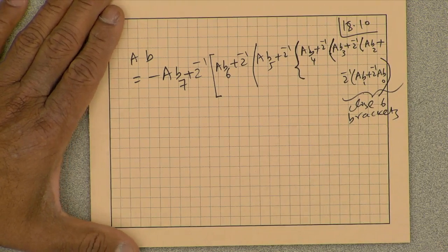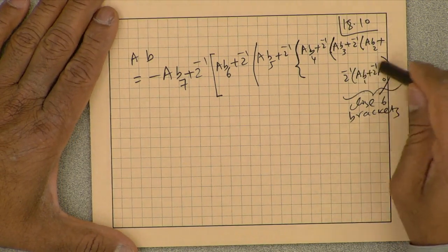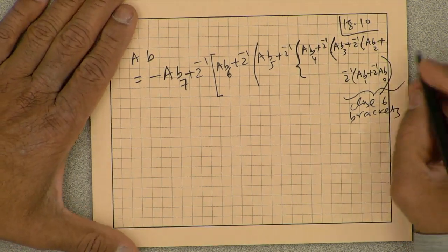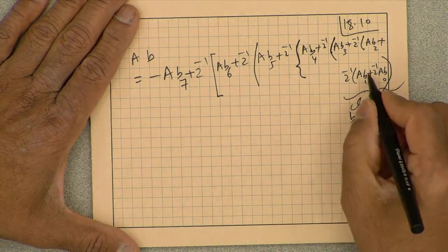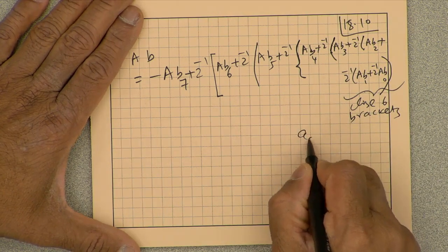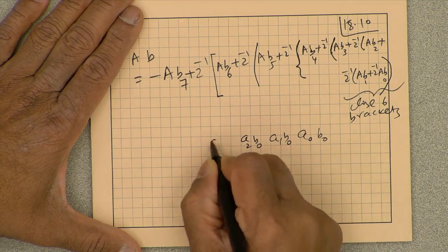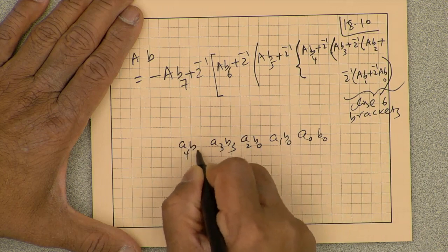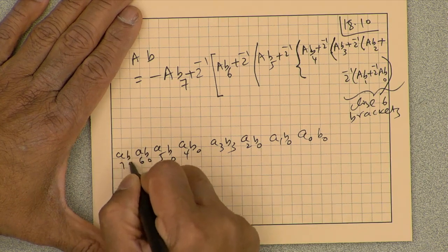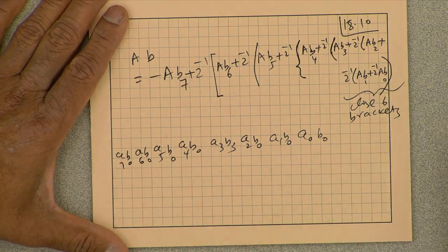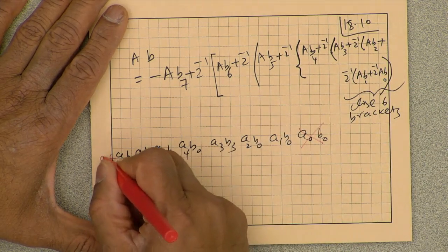All right. Initially I was writing these down one by one, as you can see. But now think about it: we are adding. Let's go back to just one of these. So a b 0 is a 0 b 0, a 1 b 0, a 2 b 0, a 3 b 0, a 4 b 0, a 5 b 0, a 6 and a 7. That's a times b 0, and times 2 to the power minus 1 is going to throw that out and sign extend a 7 b 0.